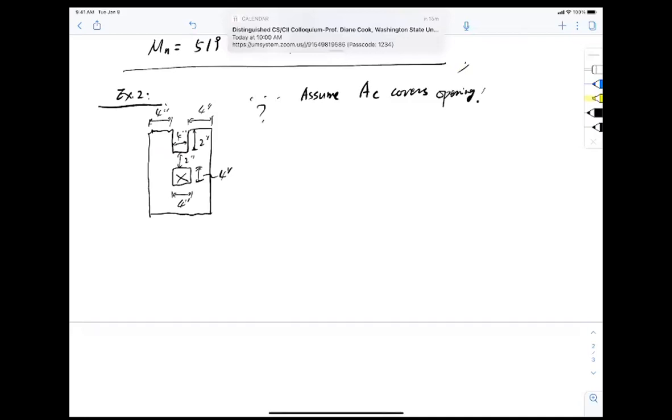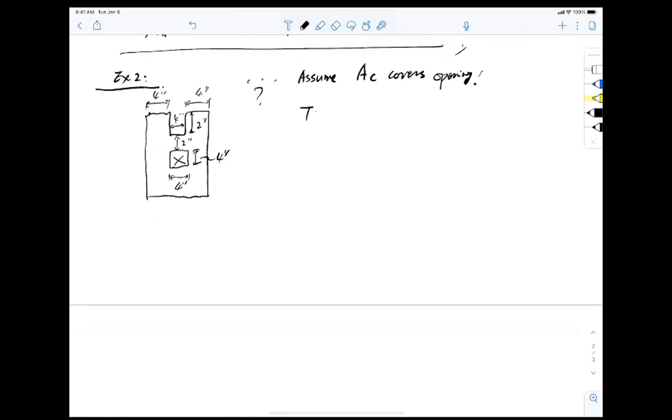We just assume that. Okay, so how can we assume that? Simple, right? So now tension force T equal to AsFy. You don't have to write this. We'll repeat this in the next lecture, okay? But I just want to give you a start. So tension equal to AsFy always, right? And let that equal to 0.85 f'c, and say the total compressive area is Ac. Make assumptions, right? So now I can get Ac equal to AsFy divided by 0.85 f'c.